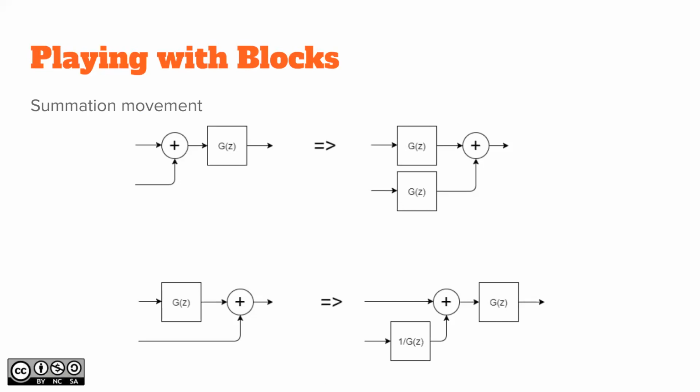Since these transfer functions are also linear, you can also move the summation either before or after. If you move this transfer function to the left-hand side, then of course you need to put that block on the left-hand side on both of these inputs, and it's the same as that one. Yeah, simple.